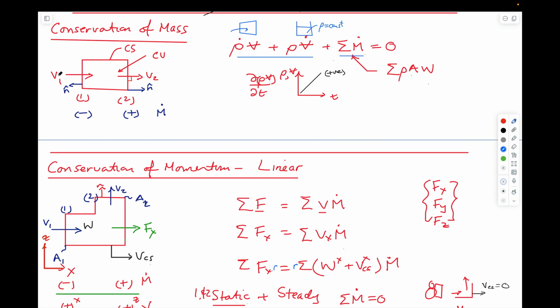And this is a mass rate, a volume rate in, and a normal to the boundary velocity, which is opposite to it. The dot product is negative. So this velocity would be a negative velocity, corresponding to a negative mass rate, which is a mass rate into the volume. So we can use that to define conservation of mass.